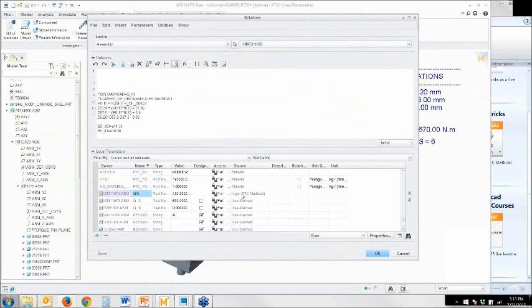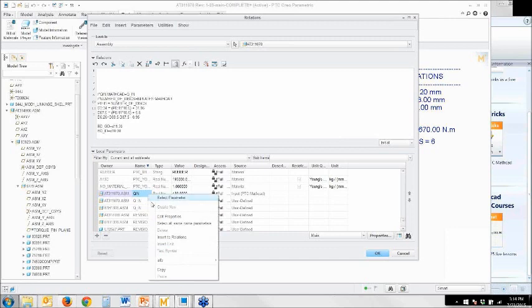That shows that whatever we're getting from Mathcad, it's passing that information in to Creo. We can then use that in the relations to assign it to different variables within Creo. And likewise, you can also pass data out to Mathcad as well.